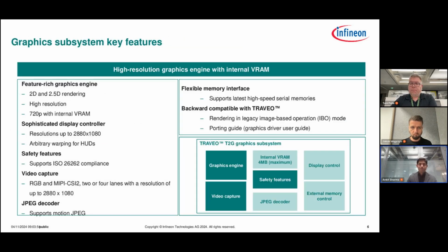So this is about the graphics subsystem. We have a very high resolution graphics engine with an internal VRAM, depending upon the device. Some devices have 2 meg, some have 4 meg VRAM. It has a very feature-rich graphics engine with smart rendering technology, where we can have a feel of 3D with the 2.5D engine.